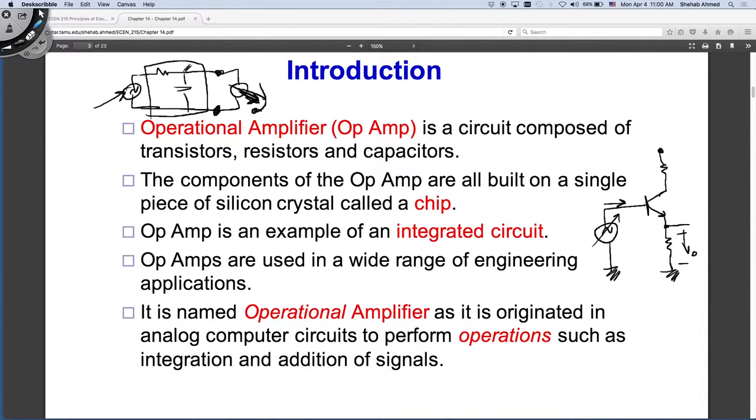But it takes its current. Remember, the current is coming in from this source here. Our output voltage here is governed by Kirchhoff's voltage law: the output is equal to the input multiplied by this impedance over the sum of the impedances. That's the voltage divider rule. This is not a logical way to run a motor.